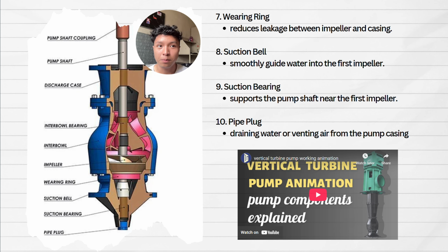So how does the turbine pump work? Briefly I can explain that. First, the water enters through the pump inlet and then the impeller spins, creating velocity, which is kinetic energy, and the diffuser converts velocity into pressure, lifting the water up via multiple impellers, and water is discharged at the surface for distribution or use. For further explanation, you may go to the YouTube link I provided below.